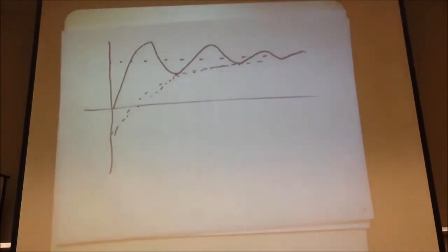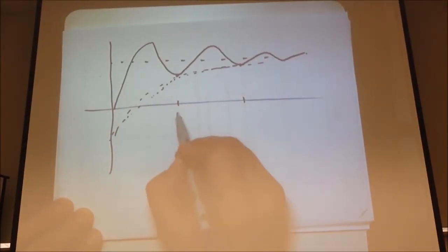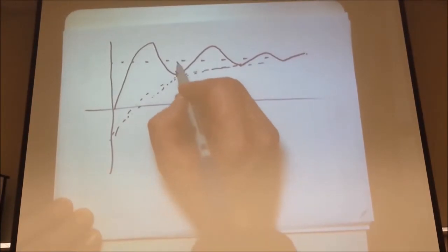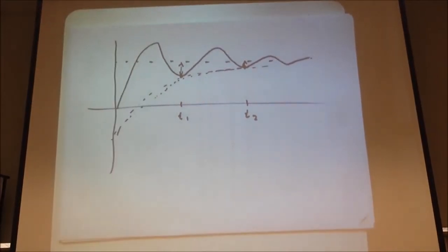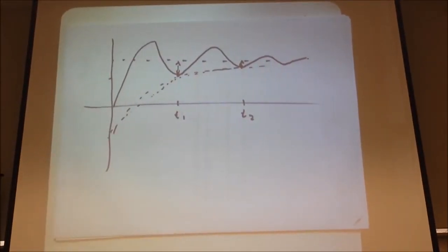Well, in this particular case, with this DC offset, we still have a t1 and a t2, but our V, or I, is the offset here. So it's always relative to our DC steady state term. That's a thing to pay attention to. If you actually just used this voltage here, then you'd have a problem.